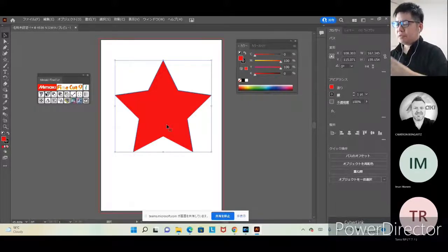If you do the simple crop mark cut, the crop mark cut without ID cut, you need to add the crop mark from FineCut, because there's no capability from the rastering to send cut data to a cutting plotter directly. It can send cutting data to the cut server for ID, but it won't send directly to the cutting plotter. So for print and cut without ID, without a cutting server, you need to add a crop mark from FineCut. How do you make a crop mark from FineCut?